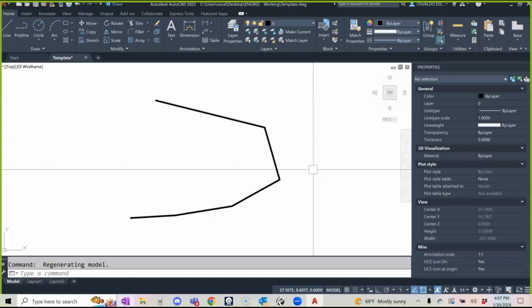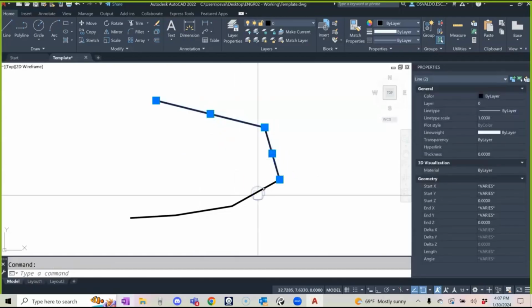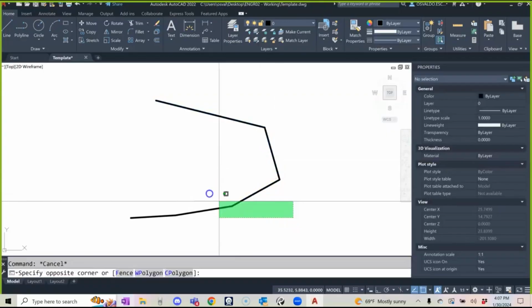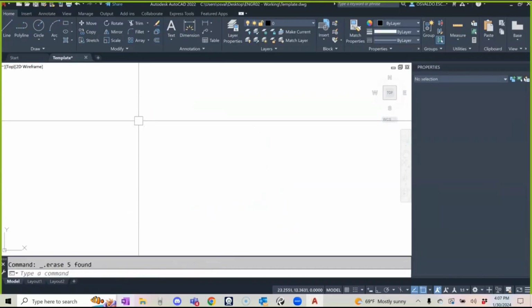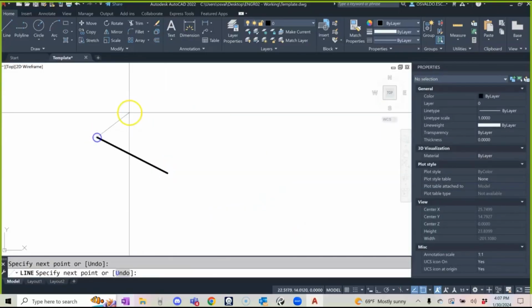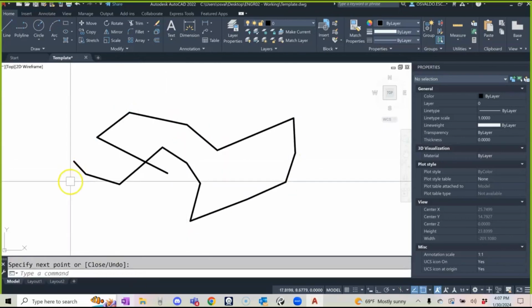Okay. Let's suppose that I want to select something. How do I select it? Left click and I will select it. Actually, let's create a line. If you have not created a line, there are a couple of ways of creating lines. You can type line, or you can type L spacebar. L spacebar. And then just click, click, click anywhere you want. Spacebar to terminate, or escape to terminate. Does that make sense? L spacebar.